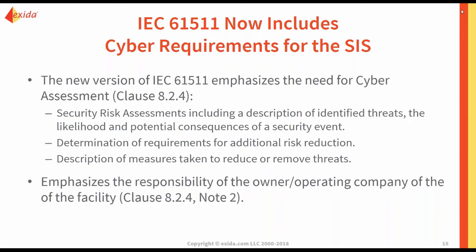The new version of 61511 emphasizes the need for a cyber risk assessment, including description of identified threats, the likelihood and potential consequences of a security event, determination of requirements for additional risk reduction, and the description of measures taken to reduce or remove the threats. It definitely emphasizes the responsibility of the owner operating company of the facility to do the cyber risk assessment. And so it's something that engineering needs to take a good look at.